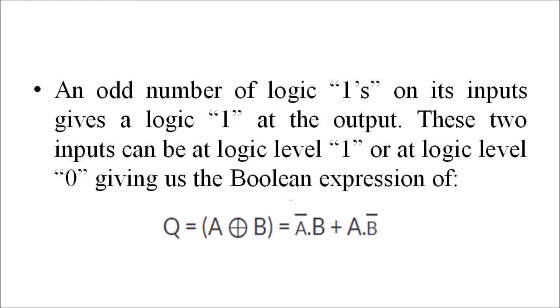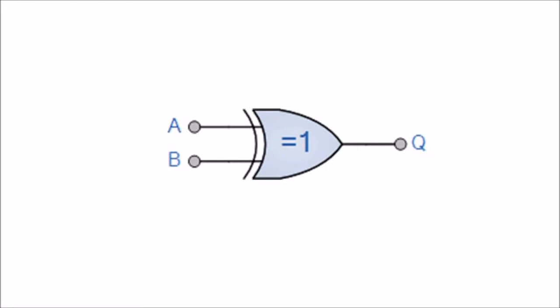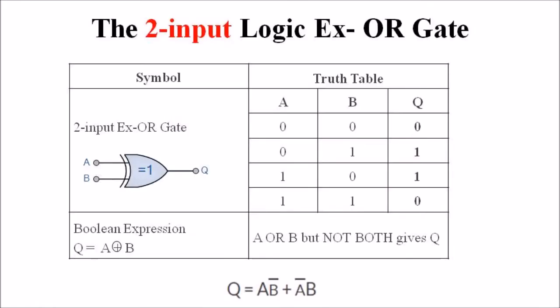The exclusive OR gate function, or XOR for short, is achieved by combining standard logic gates together to form more complex gate functions that are used exclusively in building arithmetic logic circuits, computational logic comparators, and error detection circuits. When we consider the two-input logic XOR gate, it is basically a modulo 2 adder, since it gives the sum of two binary numbers, and as a result it is more complex in design than other basic types of logic gates.